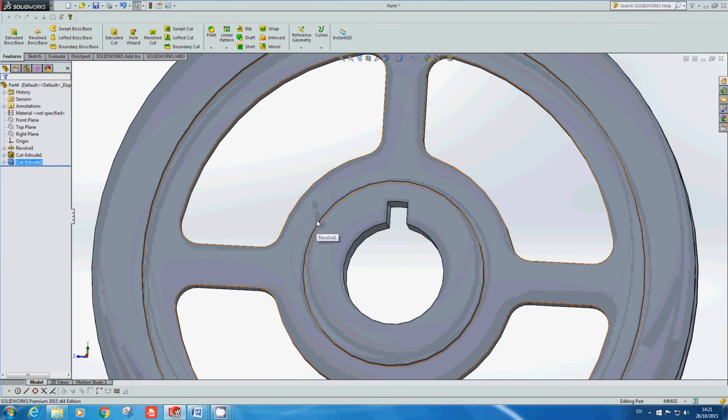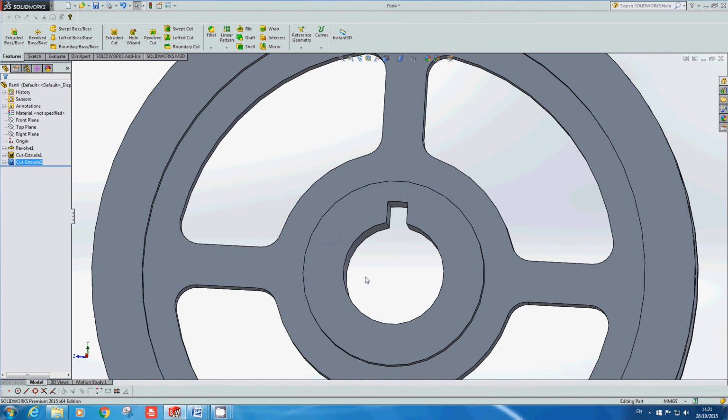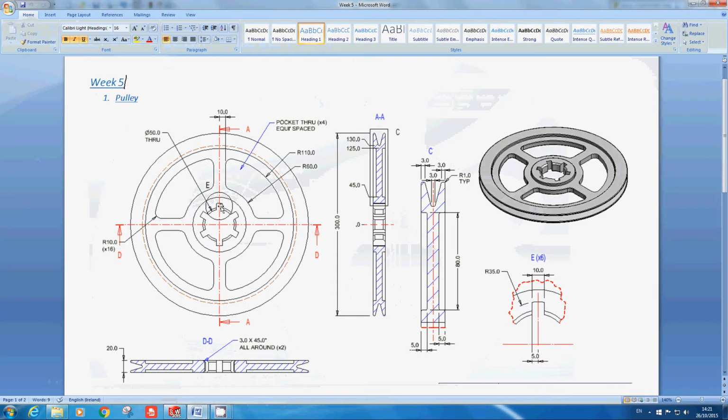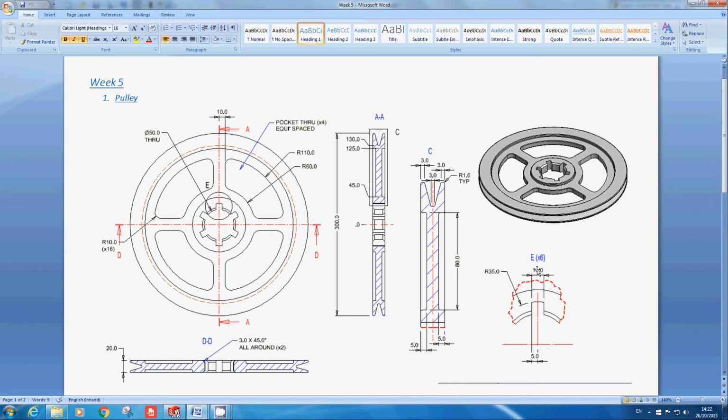So let's pattern it. Just quickly go back and see if we're missing anything. No. So that's the tooth I've just drawn. Now I just need to pattern it 6 times. So 1, 2, 3, yeah, 6 is 6. And again the view is saying by 6, so that detail view here, if you come across here, it's by 6, so everything dimensioned in it is by 6 around. So let's pattern it.